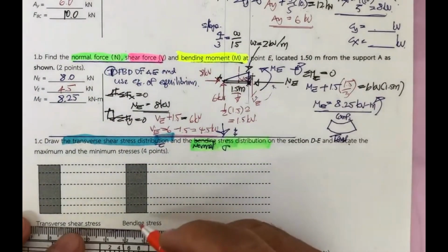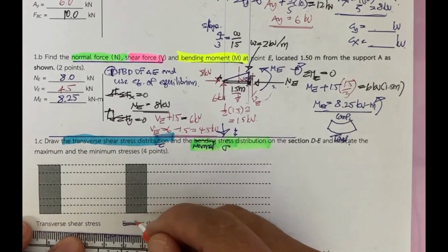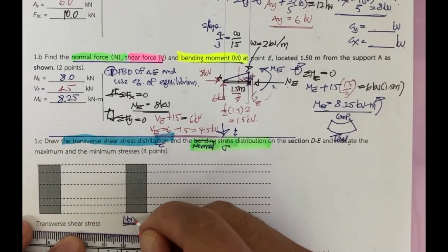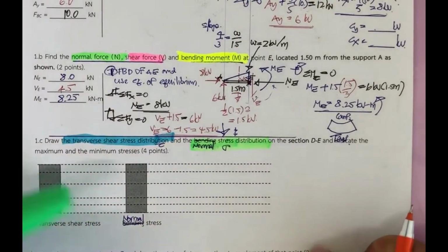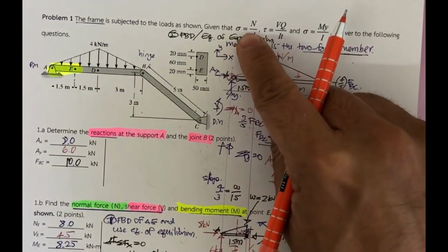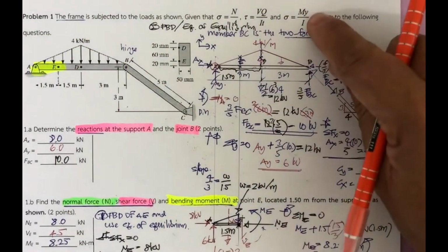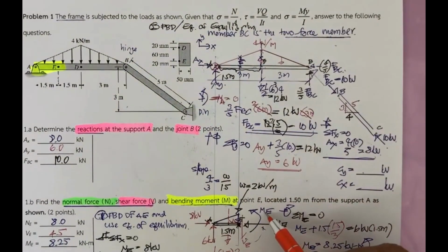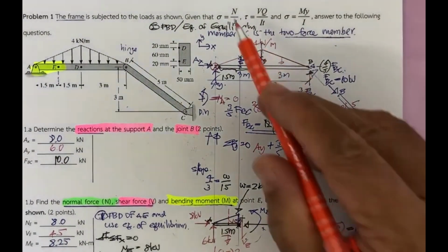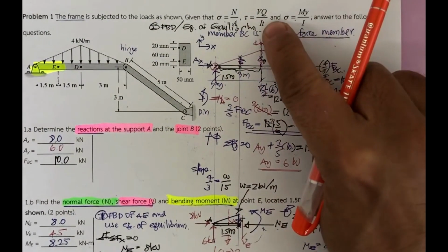Okay, this one is not kind of correct. This is going to be the normal stress. And from the equation that you have on the top, this is normal stress due to what? Due to the N sub e. This is the normal stress due to the moment M sub e. So the normal stress will come from two portions. However, the shear stress comes from this.